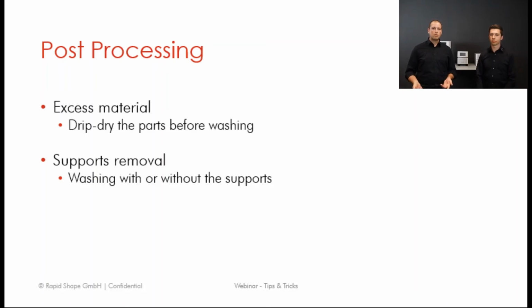Please note also that if you do have supports, there's lots of liquid resin caught in between these members, which will also contaminate your cleaning process a lot faster. So just be mindful of that. Always use a base grid when you're using supports. If it's a nimble part, probably remove the supports prior to washing. If it's a strong part, then you can probably leave it on there. But it's important to note which post-process for the washing you are using and how it will affect your printed model during that wash cycle.